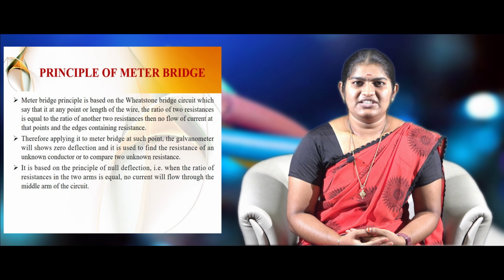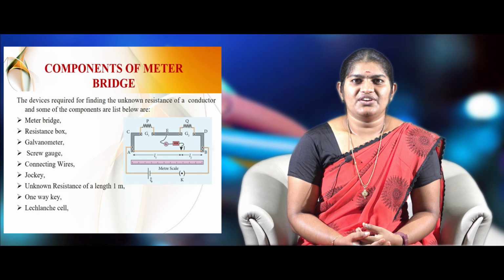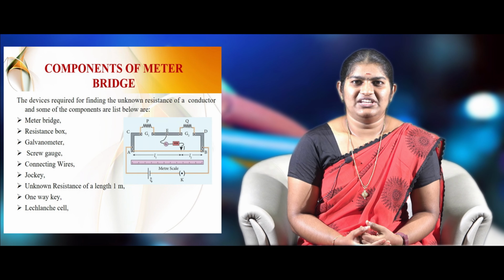It is based on the principle of null deflection. The ratio of the two arms of resistance is equal when no current flows through the mid-arm of the circuit. Next we are going to discuss the components of the Metre Bridge.